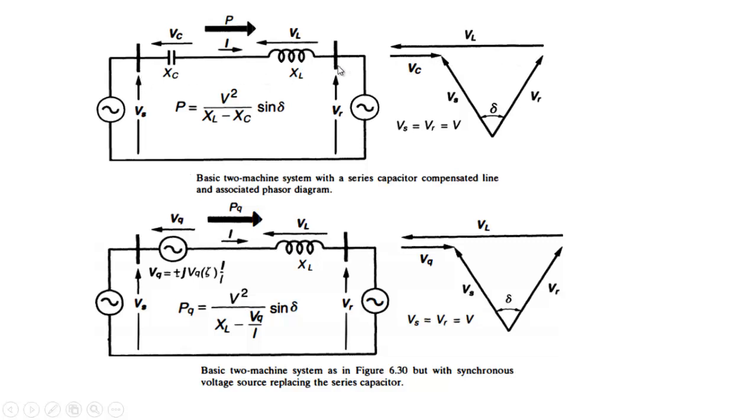Let us say the net reactance will decrease, the current will increase, and the voltage across this will now be greater as compared to without this Xc, because the voltage difference remains the same. So as net reactance decreases, current will increase, and the voltage drop across will increase. Now what will happen to this voltage?